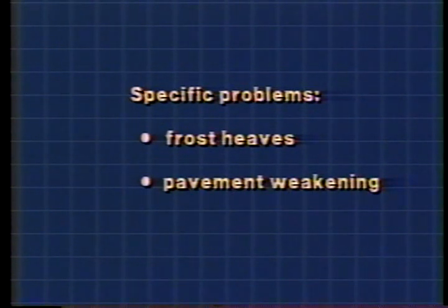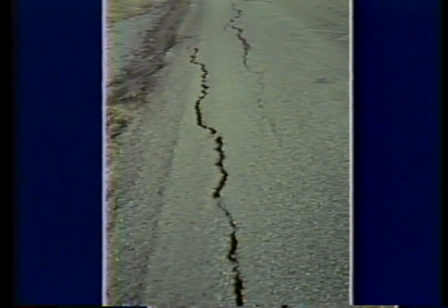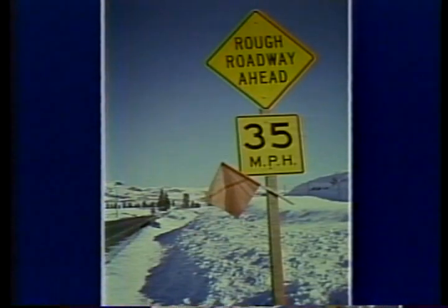This video will discuss these cold weather-related pavement problems and will present guidelines developed from recent research that are intended to help road maintenance personnel from state departments of transportation, cities, and counties deal with similar problems. Frost heaving in pavements may be relatively uniform and may appear in the form of longitudinal cracks near the pavement edge, or as heaves and cracks following the flow of groundwater, which result in traffic signs like this.